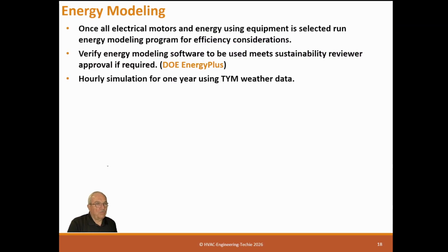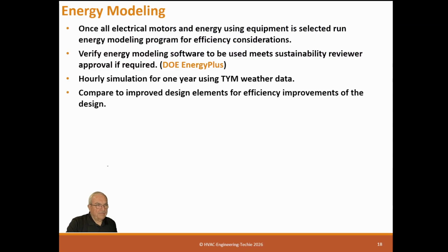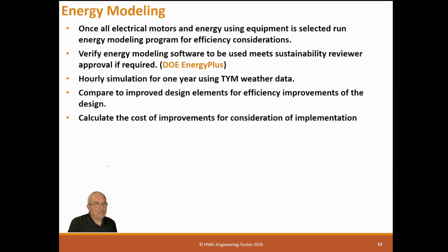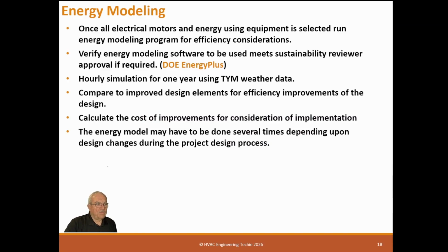Hourly simulation for 1 year using TMY weather data. Compare to improve design elements for efficiency improvement of the design. Calculate the cost of improvements for consideration of implementation. The energy model may have to be done several times depending on design changes during the project design process.